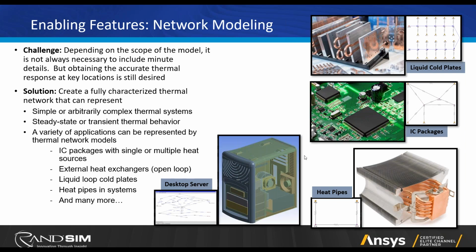Once you have this model, you can do very, very quick iterations, which do take into account heat. So maybe instead of exporting to IcePak and importing the results back every time, if you know you're going to be doing, let's say, a long optimization of some of the electrical properties of a PCB, for instance, one could make this model, attach it in the electronic solver, and then solve very quickly while still having a realistic idea of what's going on thermally.